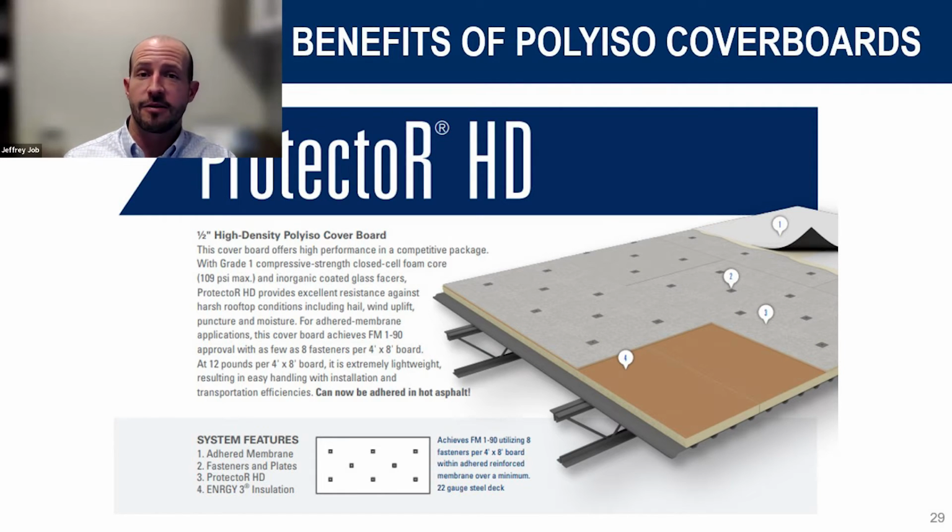It is significantly lighter than a gypsum product cover board, on average probably 4 to 5 times lighter than your traditional gypsum board. So that's a nice benefit over the gypboard products. Again, from a compatibility standpoint, a lot of it's just going to be driven by what makes sense for that project. If it's a super high compressive situation, or there's a really high fire rating, things like that might drive you to gypsum. For the vast majority of system requirements out there, you can easily get away with an HD ISO cover board from a performance standpoint, as well as save yourself some labor.